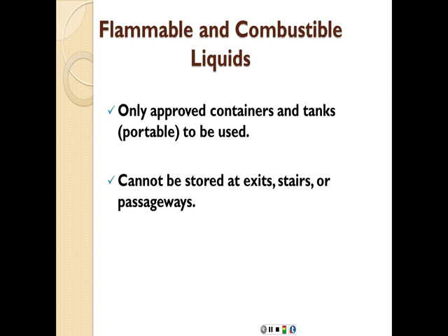For flammable and combustible liquids, only approved containers and tanks, which are portable tanks that we're talking about, are to be used. It cannot be stored at exits, stairs, or passageways, because again that defeats the purpose of an exit point in case of a fire. These by themselves are a big fire hazard, so you want to eliminate them or keep them away from the exits and the doors and the stairs.